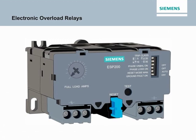In addition, electronic overload relays can detect a power phase loss and quickly disconnect the motor from the power source. This is an important advantage because without phase loss protection, loss of a power phase can quickly result in damaged motor windings.